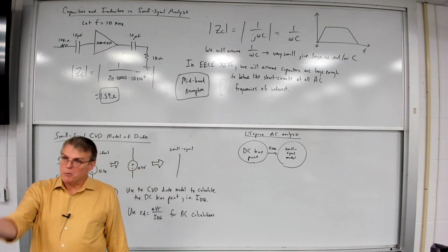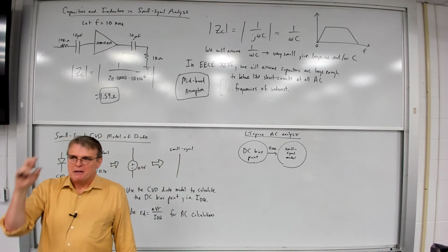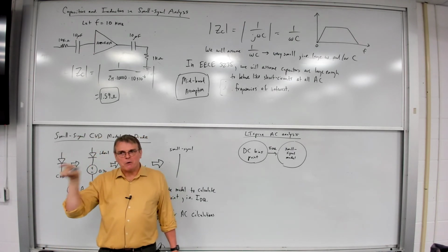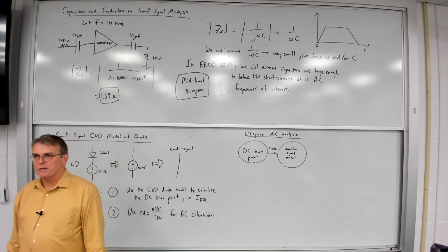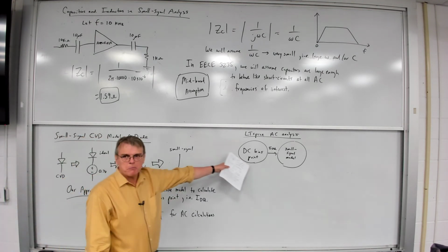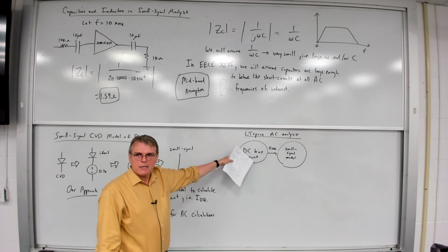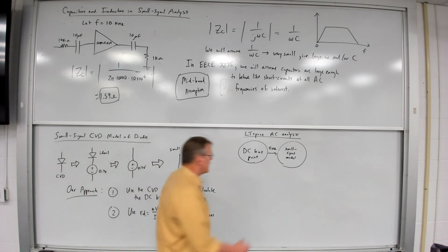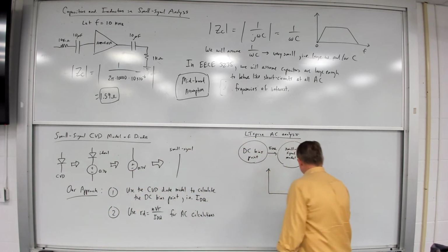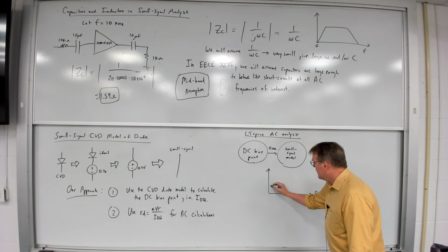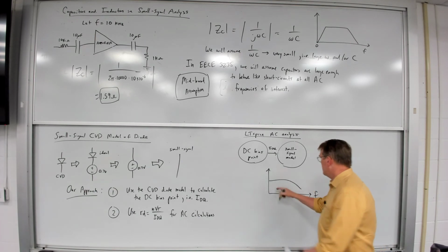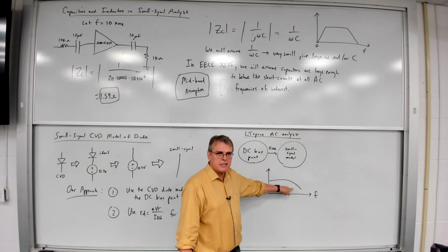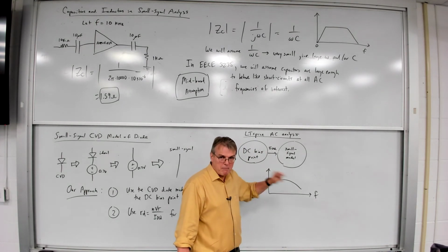So for example, in the pre-lab you guys did this week, you specify a DC bias value plus an AC value on the source when you did the AC calculation. That DC value set our bias point. Then once the bias point was calculated, then it did the AC calculations. And of course, in this case, LTspice in the AC domain does calculations versus frequency. And so you will see, for example, voltages and currents will change with frequency. And that's the influence of the capacitors that are actually in the model that you're simulating.